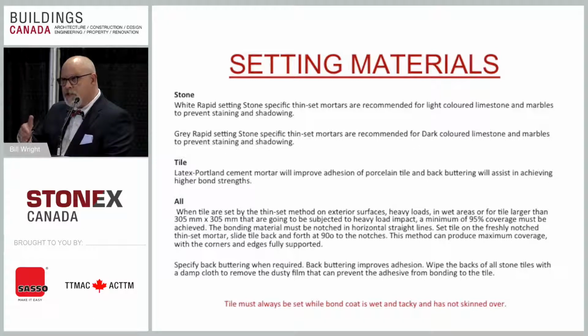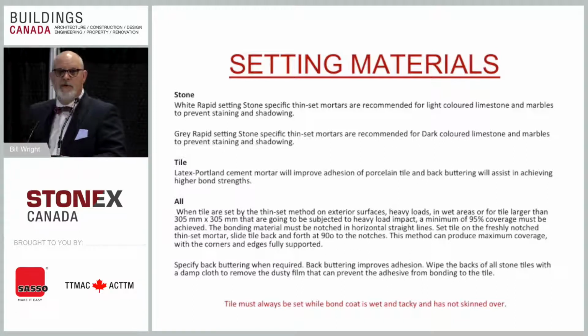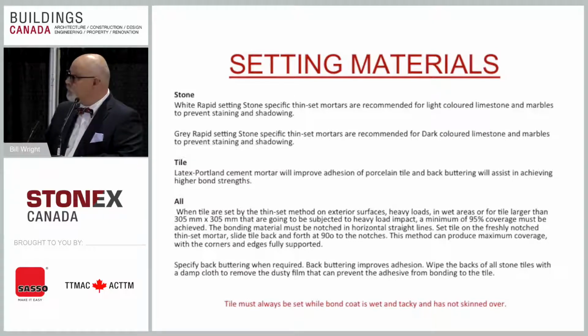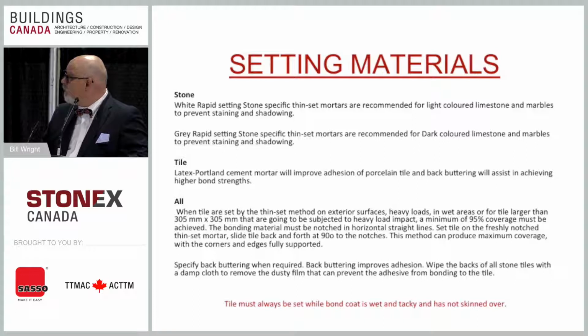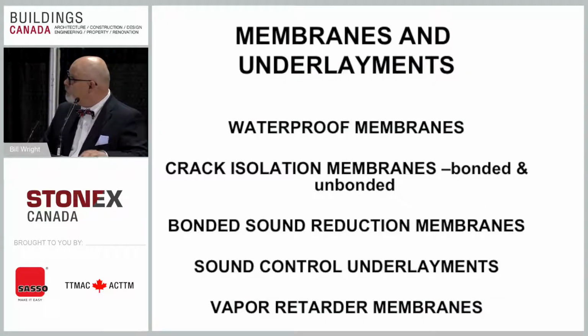Different mortars for exteriors and for interiors. So have these conversations. Make sure this is something on your checklist when you're writing a specification. Have we spoken to the manufacturer or the supplier and got their guidelines on what types of mortars to best use? We move on to things like mortars and underlayments, waterproofing membranes.